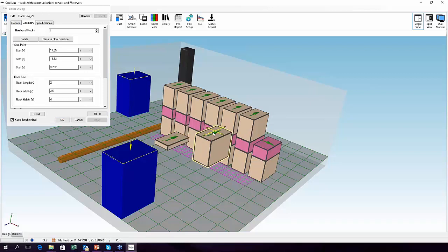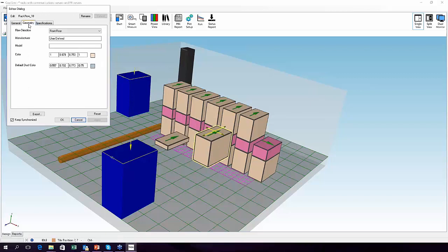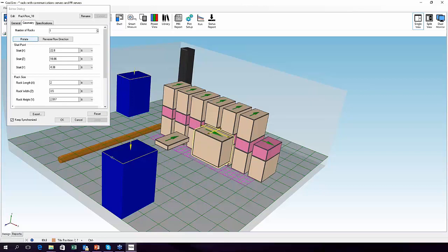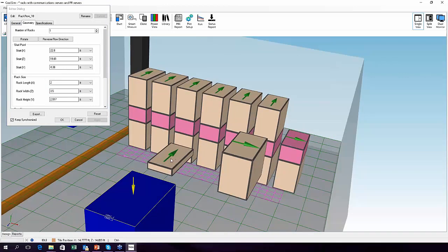And then you want to put one the other direction, so you do it again. Maybe we take this one and rotate it 90 degrees. This could be the communication server. Change the orientation so that it's 2 feet in this direction and 3.5 feet in this direction. So there's my sideward server. Now I just need to orient it in the correct position so it sits on top of this one. I can't quite remember what we did. In terms of U, its height was 4 and it started at 25. So I want this one to start at 30. I just edit this one, and I want the start Y position to be 30. Yep, 30. And then I just drag it over.